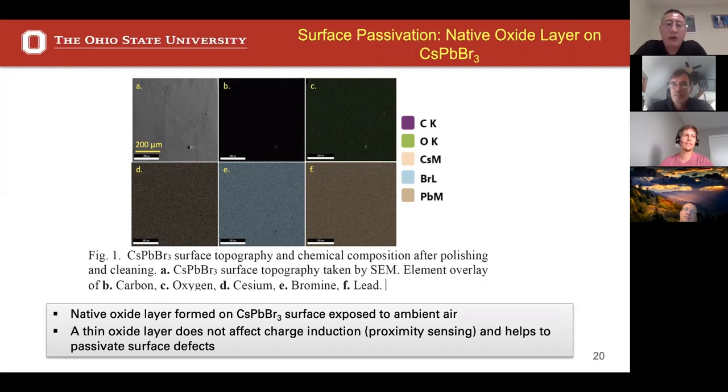Yeah, absolutely. I'm very interested. I would be very interested to have this collaboration, actually, to try some passivation process to see how that affects performance of the device. So far, 2 to 3 nanoamp at 200 volts is pretty good, but I think we still have a lot of issues with the bulk leakage current or the defects in the bulk. So that's another potential improvement that can be done.